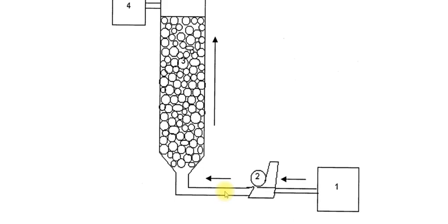If the reactant is in the gaseous phase, it enters the column from the bottom and moves upward, then is removed from the top of the column. If it is a liquid reactant, then it will move from top to bottom. This fluid exerts a force on the catalyst. So we will discuss how much force is exerted on the catalyst.